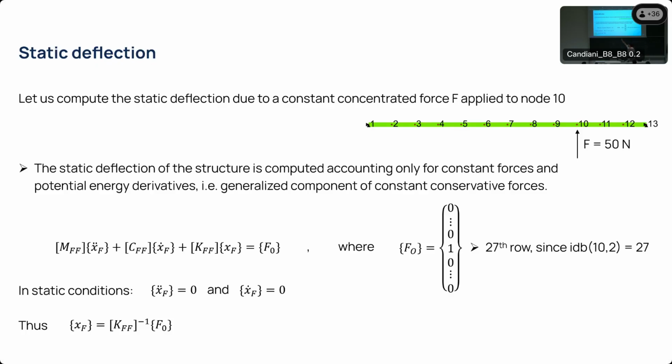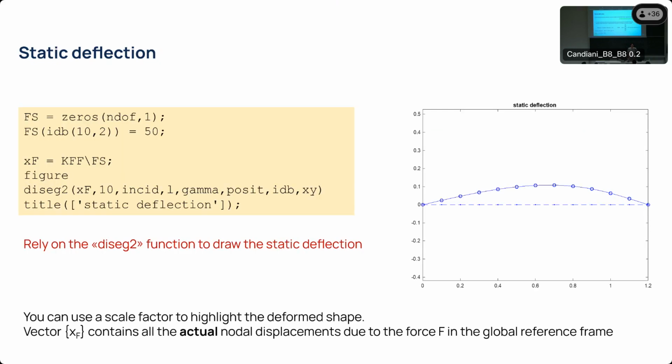You feed it into that force vector, and then you multiply that force vector by the inverse of the stiffness matrix, and then you get the displacement of all the points on the structure based on its weight, the weight of passengers, the weight of cars, the weight of anything you place on the structure. After you do this, you can just use the plotting functions we gave you to find the general shape, the general arc, in this case, of the structure. Remember, in this case we are just giving a vertical force going up, so we shall expect the structure to move upwards, because we're just deforming in this direction.